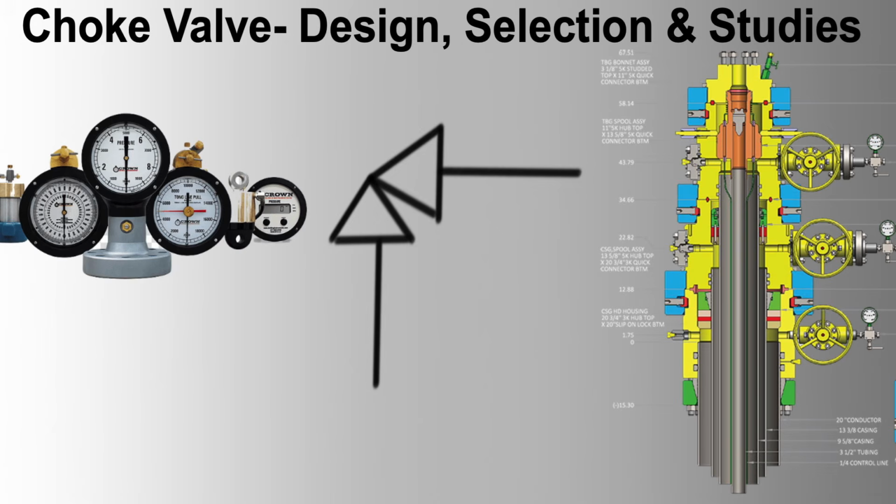4. Data transmission failure. Problem: failure in data transmission from sensors to control systems. Solution: use high-quality shielded cables and redundant communication paths. Implement wireless telemetry systems where feasible.